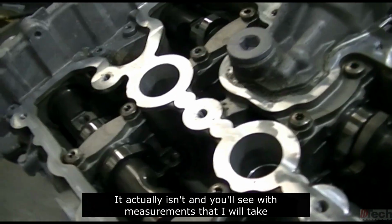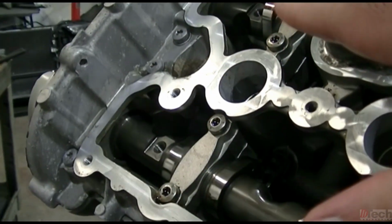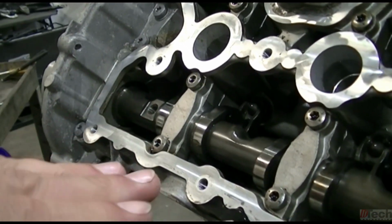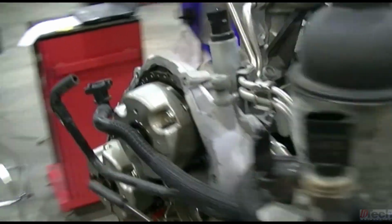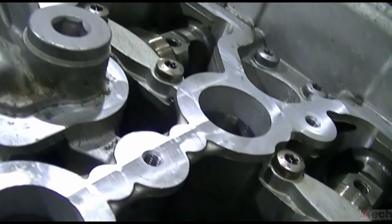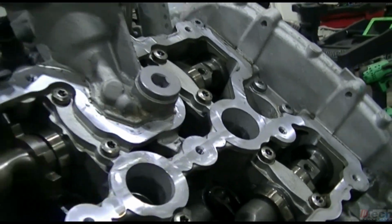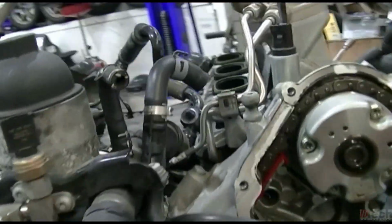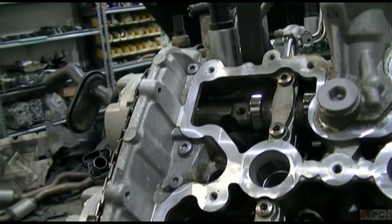It's obviously hard to tell on camera, but I believe that both of them might be off, but it definitely looks like the exhaust is more shifted inwards. Again, very difficult to tell on camera, as opposed to these two, which are pretty much perfectly flat. Obviously, they are, because the timing tool goes in without any extra effort. So that was the first thing I noticed, and I just wanted to go about getting a better idea.